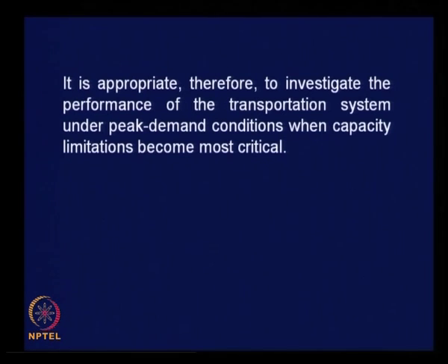It is appropriate therefore to investigate the performance of the transportation system under peak demand conditions when capacity limitations become most critical. This is the most important point to be remembered. There is no point in taking the daily average and doing your route assignment.